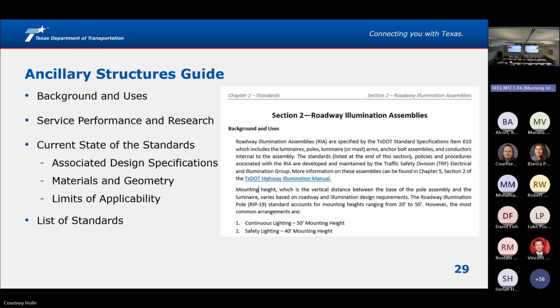So there is some need for policy. I know in our high mast illumination poles, our handholds are slightly smaller or slightly bigger than what the spec allows. Well, based off of past practice, we're moving forward with that. So we need to document when we're deviating from AASHTO, kind of like what we do with bridge. I know in bridge, we also have a bridge design guide that would have commentary, right? I would prefer not maintaining three ancillary structure documents.